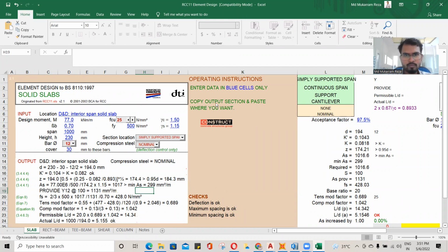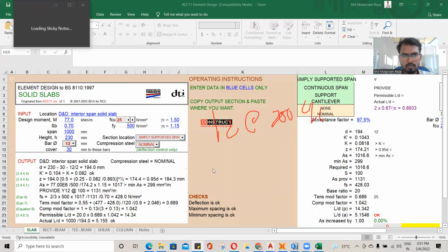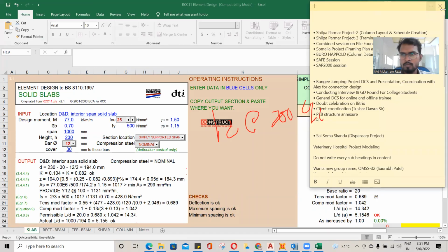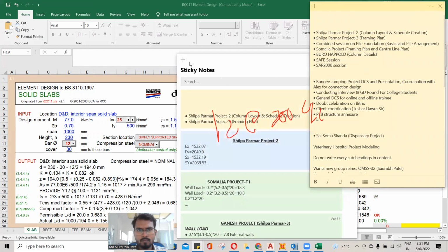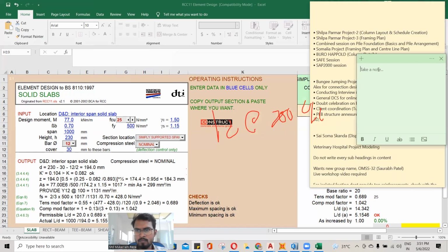Basically, for 12, when you idealize this, you cannot go more than that. I have seen people giving columns as long as 1.2 meter deep also in the same project. So you can go as long as that, but what will happen is your idealization happens in only one direction, whereas you have three directions. The stiffness and the contribution of resistance is coming from three dimensions in actual, but you are idealizing only one direction to be extremely huge compared to the other. So the horizontal reinforcements are very high compared to the other.